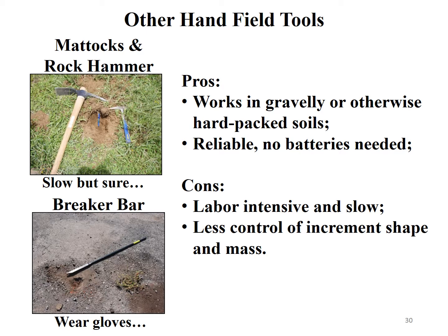This slide illustrates other hand tools that may have to be resorted to in really dense, hard-packed, gravelly soils. We encounter these kind of soils all the time in Hawaii, unfortunately. All these years we've been busting a lot of rocks, and a lot of these former commercial sites, these old sugar mill sites, etc., pesticide mixing sites where it had gravel spaced on them, heavy trucks traveling over them for many years. So the soil in these areas are densely packed, have a lot of gravel or rock in the soils, and you literally need a pick to bust into the soil.